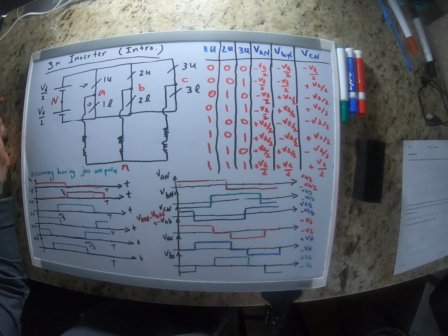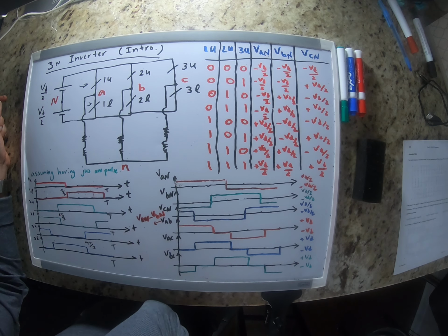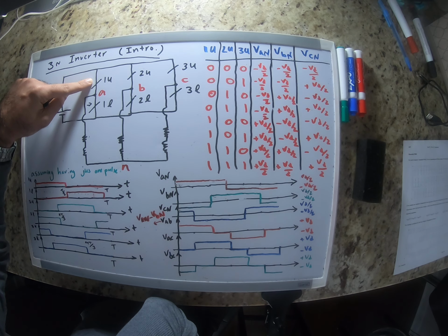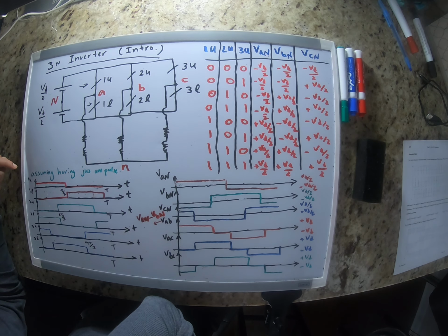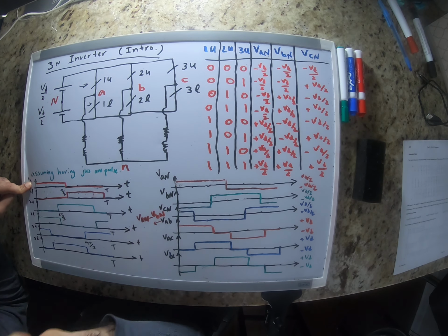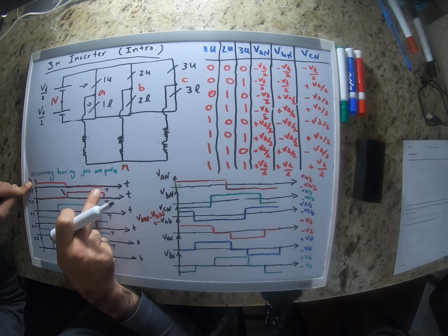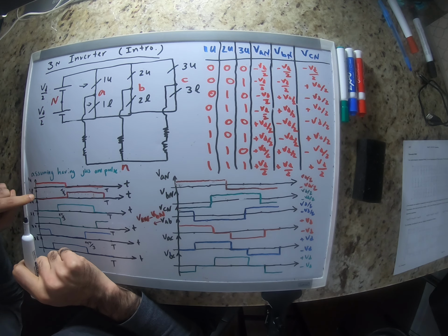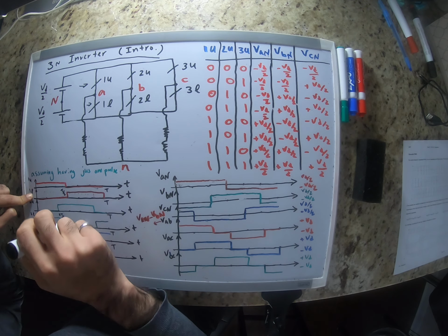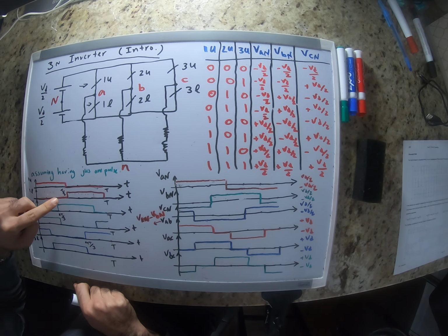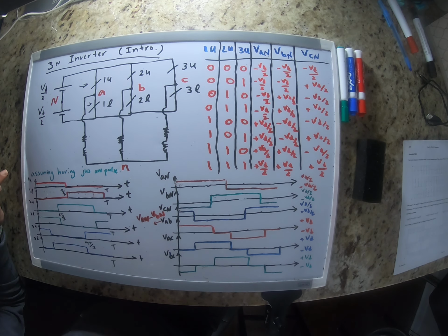Let's look at how we fire the switch for the first leg, for phase A. In this case, the switch is on for half of the cycle, so 180 degrees, or the period over 2, and off for the second half. The lower level switch is the inverted version of the upper level switch, so it's off for half of the cycle and on for the next half.